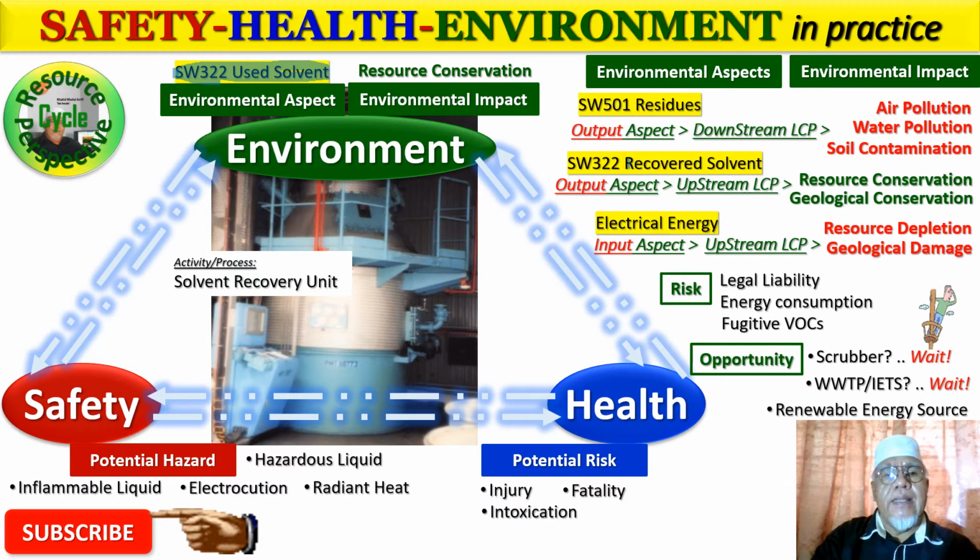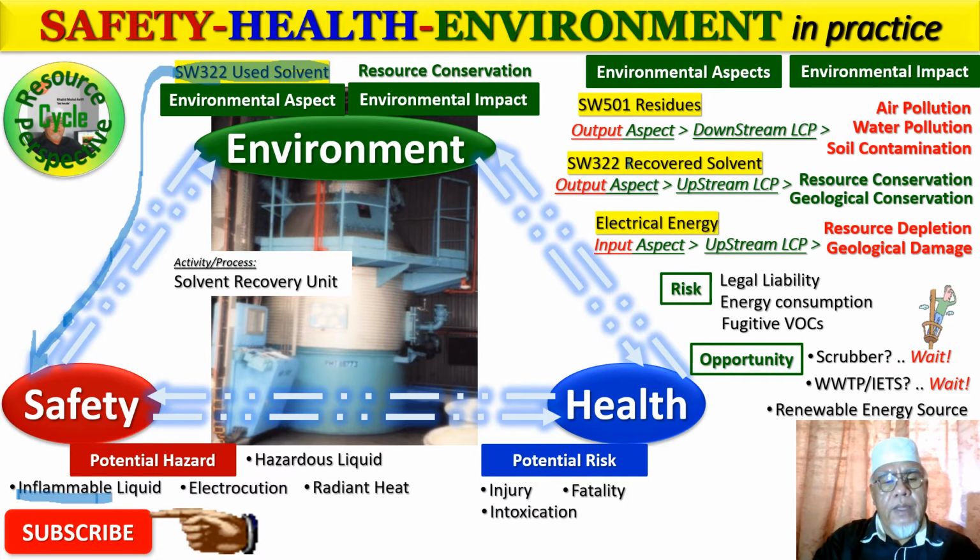And by virtue of the chemical properties of solvent, as you already know, they are perhaps a benzene ring, a petrochemical derived chemical, and the fact that most of this solvent is inflammable, if not, perhaps I would say some of them would be spontaneously combustible liquid, that is posing already a potential hazard at workplace. It can catch fire, or it can explode and cause some form of injury to human being and even fatality. So that is one association between potential hazard and potential risk.